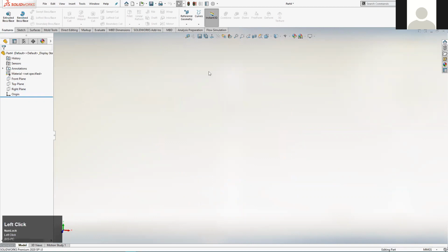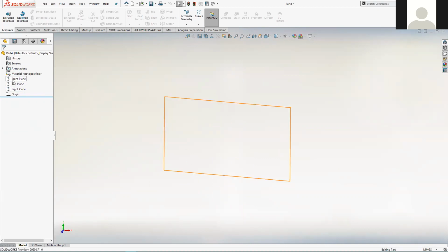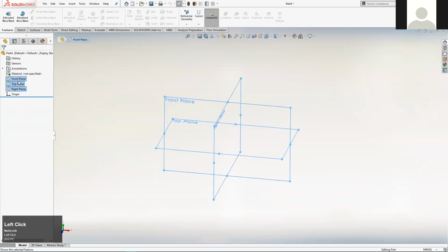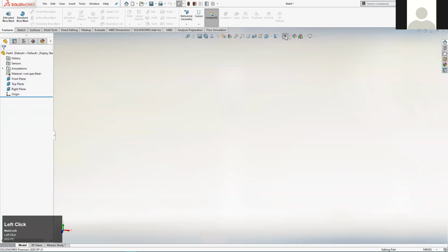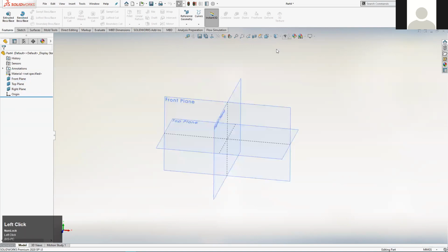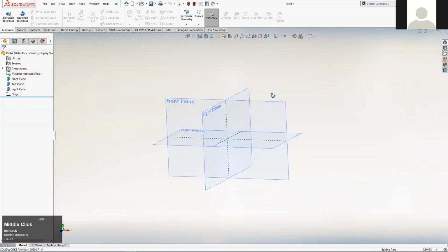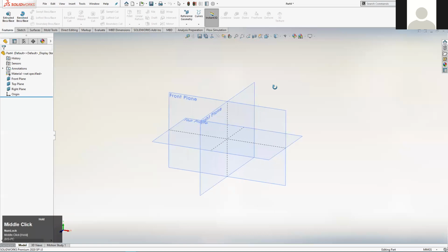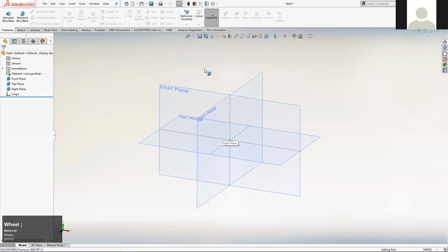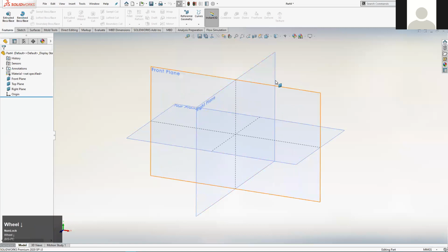And when you've got the visibility set to off or hide, they'll just be a wireframe icon, so you can quickly tell. Or you may have hide all types selected up here. I'm just trying to cover all bases here because I know certain installations of SolidWorks come in and the planes are hidden by default. So hopefully you can see your planes now.